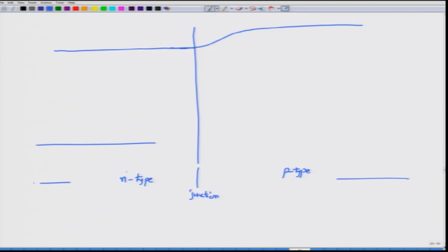I am also assuming that the n type material is heavily doped, so that I can use a plus superscript to indicate that the majority carriers, the electrons, far exceed the majority carriers of the holes in the p type material. So, this is called heavy doping, and what heavy doping does, if you remember from your p-n junction theory, is that it pushes the depletion layer which will be created at the junction deeper into the p type region. What is this depletion layer? Well, we know that when we are looking at the n type region, far away of course will be this one, but you have a valence band here, right.